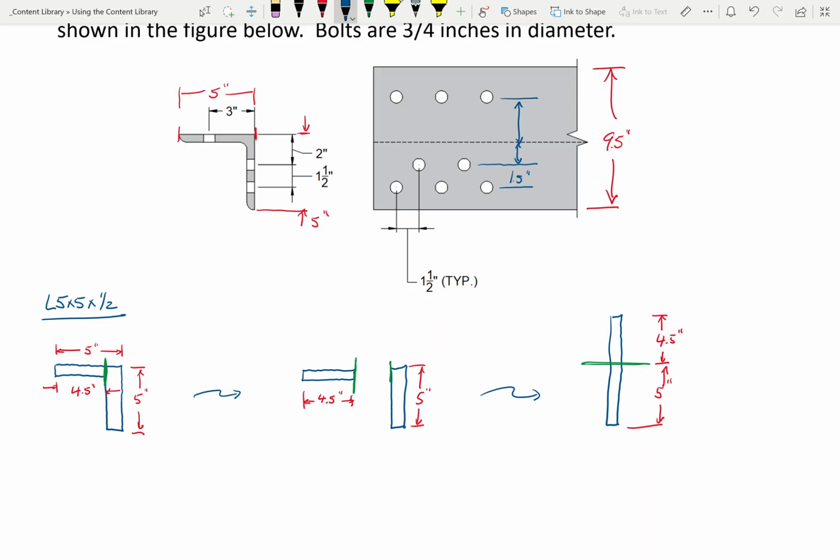So see how instead of this being 10, and instead of this being 10, it's 9.5? We cut a 1/2 inch off, right? So how about this? From here to here, it's 2. So we'll say maybe this is 2. If we say this is 3, that's going to be wrong, right? Because we'll have overlapped. So maybe what we ought to do is say this is 2.5. I propose that from here to here, it's 1.5. From here to here is 2. From here to here is 3. So we could say this dimension is 5 inches, but we'd be making the same error as if we said from here to here is 10 inches. We're overlapping, right? So I propose that this dimension is 4.5.